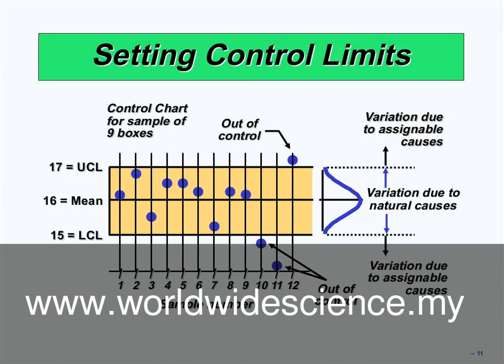When we calculate the upper and lower control limitation, we should put all of the means that have been calculated inside this diagram and see if there is any sample out of this control limitation or not. If even one point is outside this limitation, we should say the process is not under control.